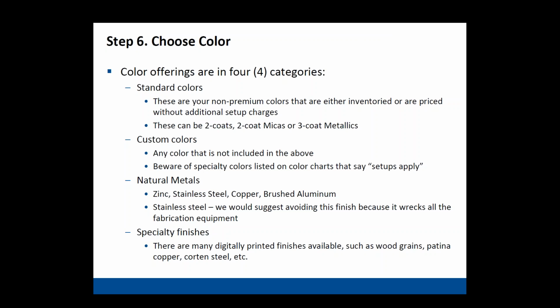What the manufacturers have to do is paint enough coil that usually produces about 20,000 square feet of material, or they have some other minimum setup charges that you are paying for, either painted coil, wasted paint, lots of other things that make it more expensive. So if you have a project that's, say, under 5,000 square feet, it's pretty important that you stay in the standard color range rather than trying to go with a custom color.